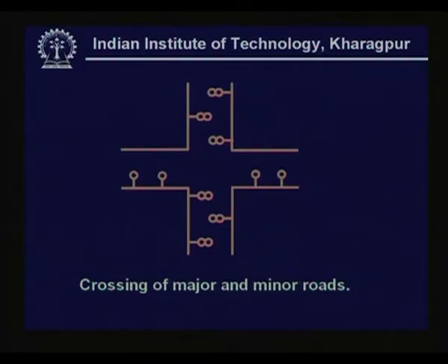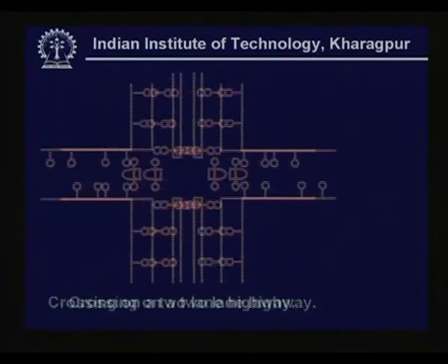There are double circles to indicate that possibly they are lamps of higher flux levels, and in the minor road we find that they are arranged only on one side, thereby making it a little lower level. Remember that the minor road needs to carry lower traffic density.